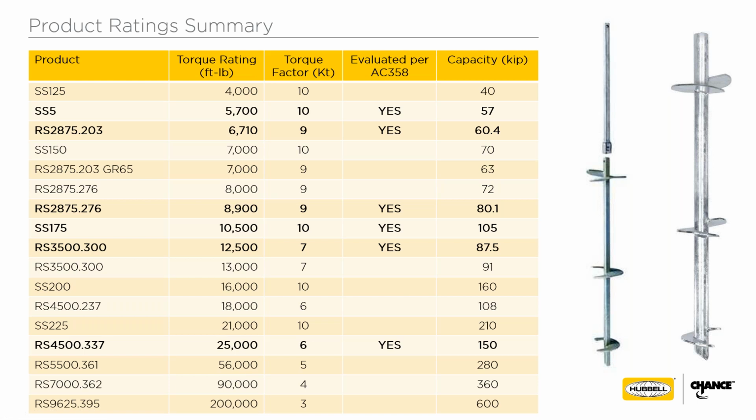Again, if you're not familiar with their method, they're much like a wood screw in terms of how they install into the ground. They advance one helical flight pitch opening per revolution, and it's very common to have multiple plate elements like you see on those photos on the side.